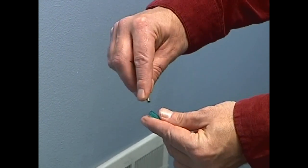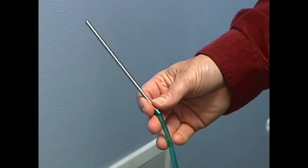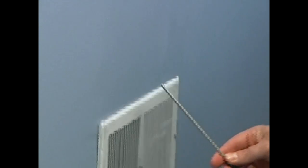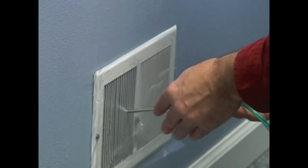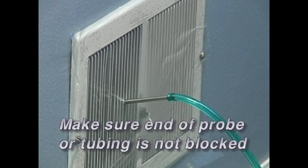First, insert the 6-inch straight stainless steel probe into one end of the green tubing provided with the duct blaster system. Now push the probe through the tape or duct mask that is sealing the register. Make sure that the end of the probe is not blocked off.